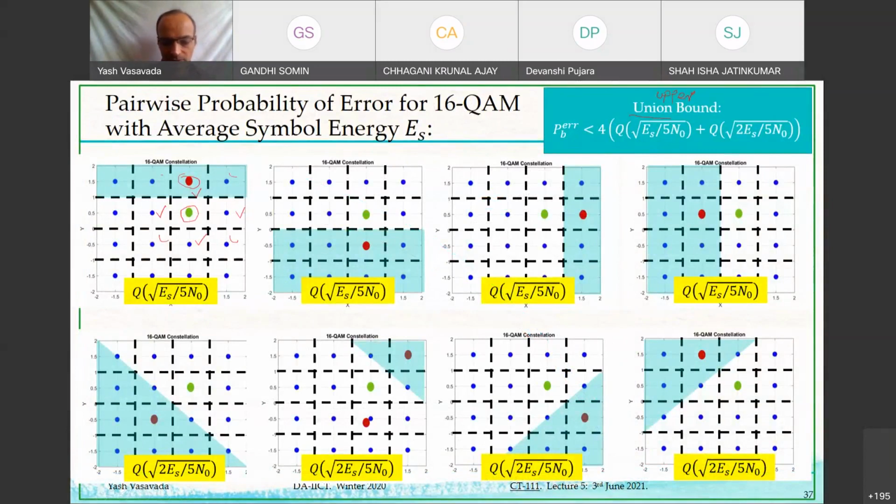In the same way, you would notice if you look at the lab manual, for the other modulation schemes, QPSK, 8PSK and 16APSK, in this lab number 8, I am asking you to do the pairwise error probability using that Q of d divided by square root of 2 N naught and just multiply it by 2.